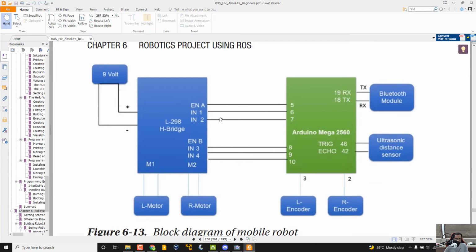And then we have seen the motor connection. Then these are the microcontroller connections. I mentioned that the motor driver is connected to the microcontroller, in order to completely control the motor driver, so we can rotate the motor in any direction. In order to rotate these motors, we have to give commands from the microcontroller. Commands in the sense these are all simple pins. We have to set these pins as high or low. High means maybe 5 volts, low means 0 volts.